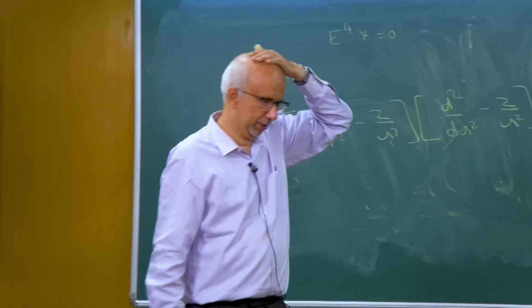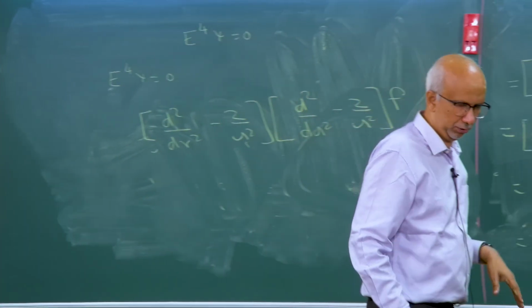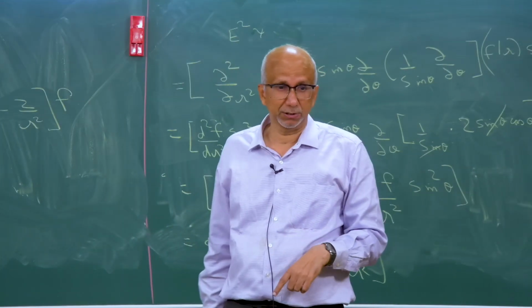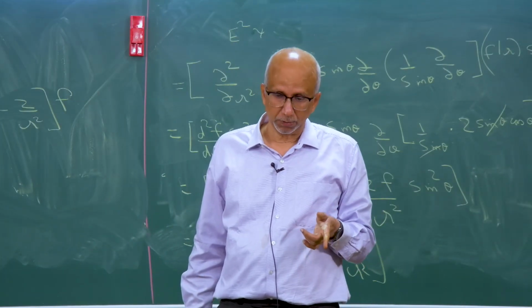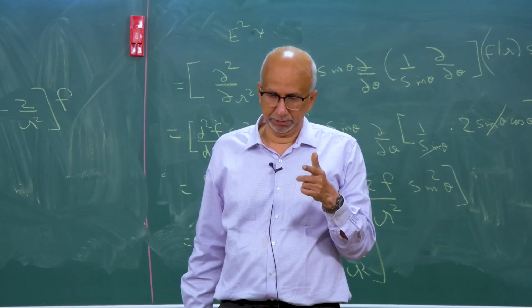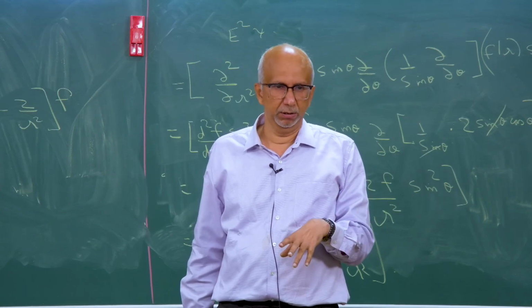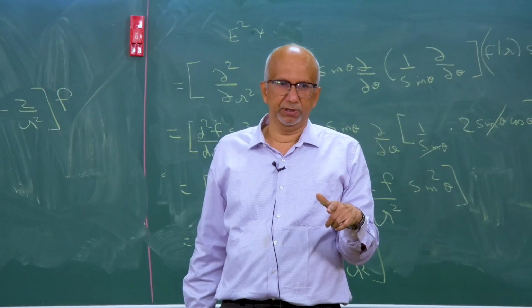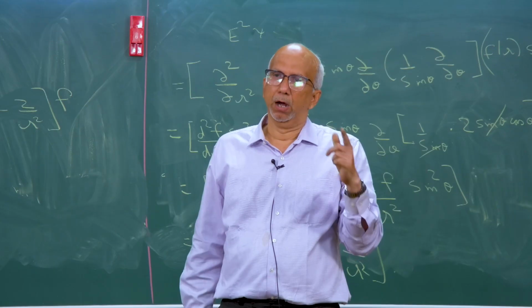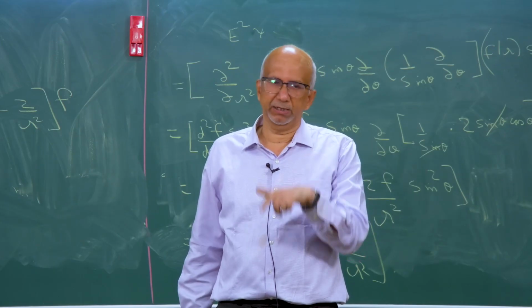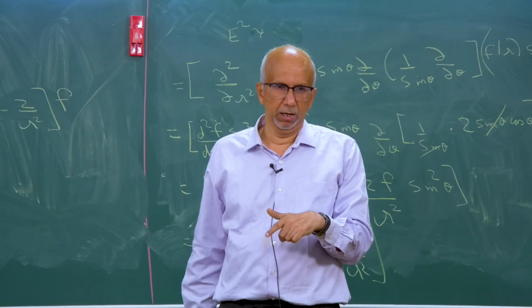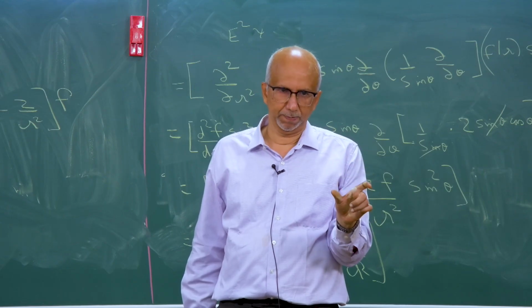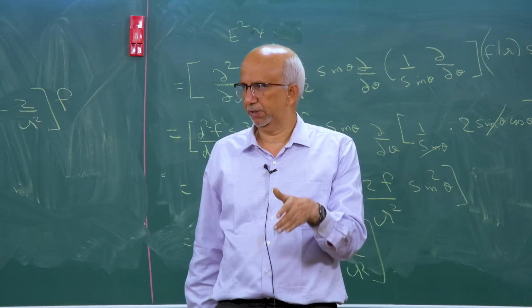Just like in cinema they have some teaser, I am going to give a teaser. What we are going to do next class is find f of r, find the stream function, find the velocity field. After we find the velocity field, we get the pressure, because you have to satisfy the creeping flow Navier-Stokes equation. So I have the velocity field, I have the pressure information.